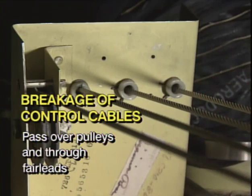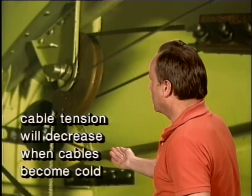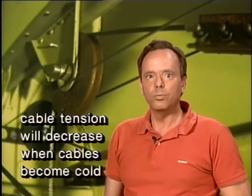All right, now the next thing we want to talk about is a cable-operated control system of an all-metal aircraft that does not incorporate a temperature compensating device, and it's been rigged to the correct tension in a heated hangar. If the aircraft is operated in very cold weather, they're going to ask you what will happen to cable tension in cold weather. Well, in very cold weather, cable tension will decrease when the cables become cold, and the reason for that is the aircraft actually shrinks more than the cables do, so cable tension will decrease when the aircraft structure and cables become cold. It's both of the two combined that become cold.